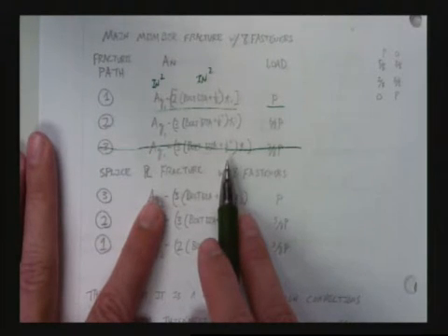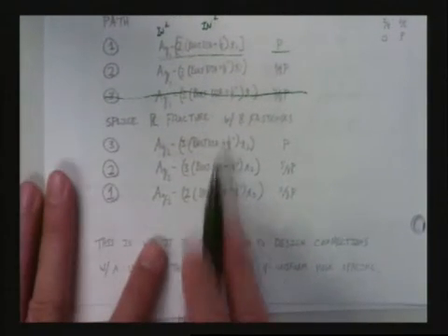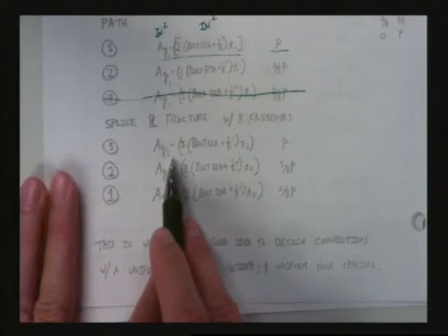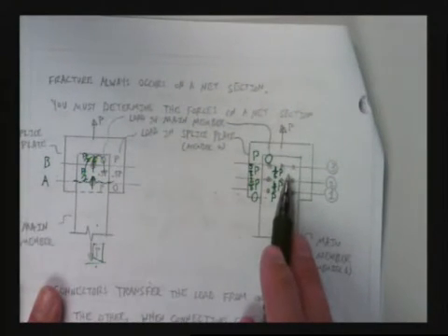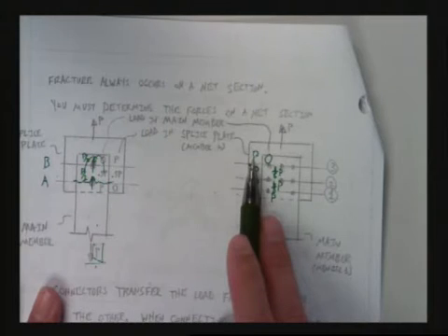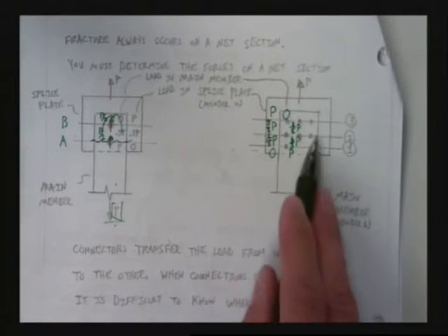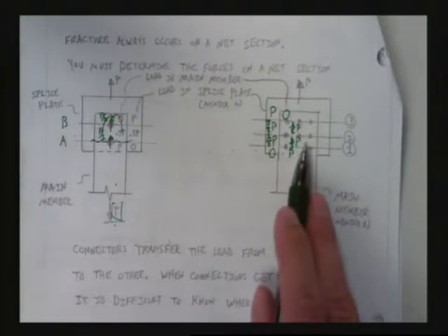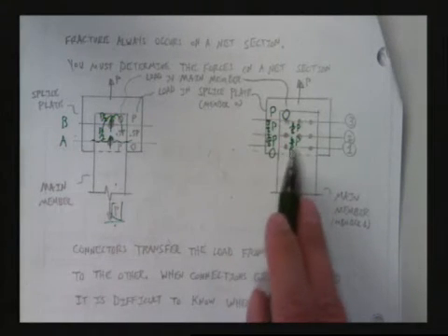You with me? Okay? Now if we do the same thing for the bottom, we'll notice it's a little different, isn't it? On this first line 3, I am subtracting out 3 bolts, right? There are 3 bolts there. But I'm dealing with a load P, aren't I? Yes? So I can tell you right now, I know for the bottom plate, it's going to fail where? Line 3, isn't it? Has to. Because it's the same area on line 2, yet the load is lower.